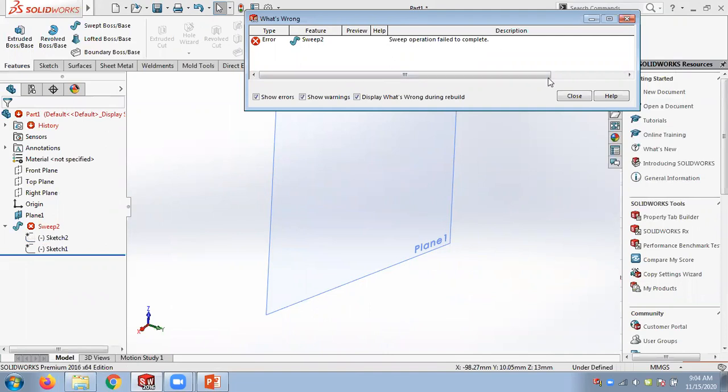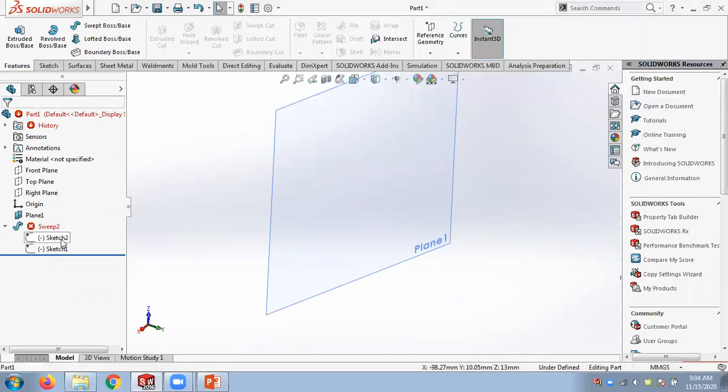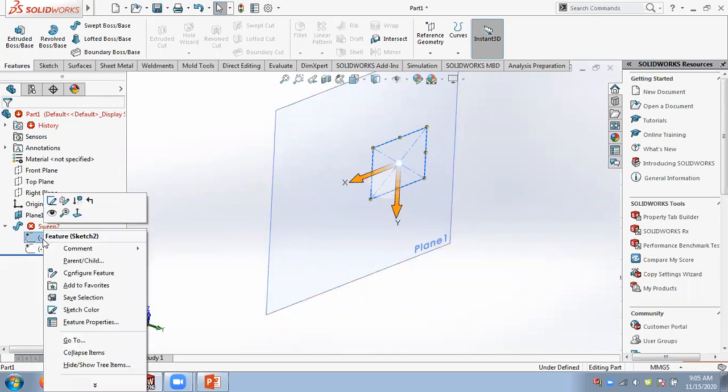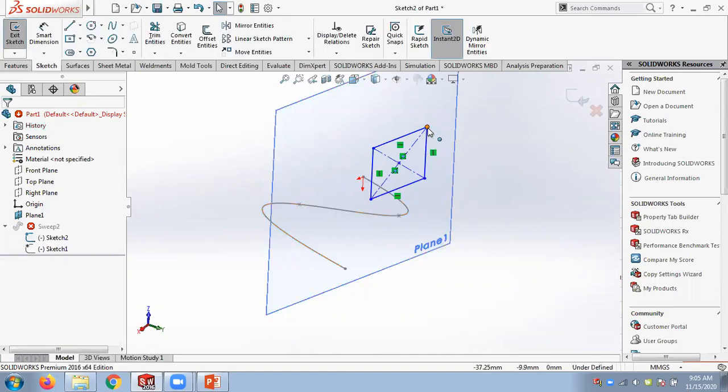So the basic idea here is my profile is really big. So when my profile is really big, I can't take these bends smoothly. Otherwise, if the bends are very sharp, you cannot generate the sweep tool. So make sure you have a smooth bend and small profile compared to the bends. So you have to have a smooth transition in these curve areas. So that's what happens here. When you have a big profile, the sweep tool will fail.